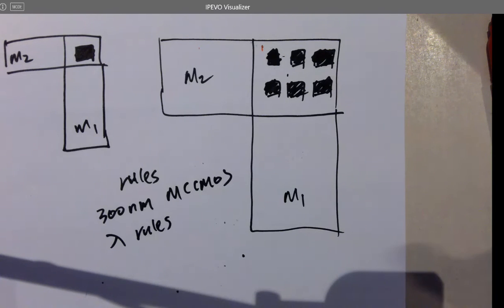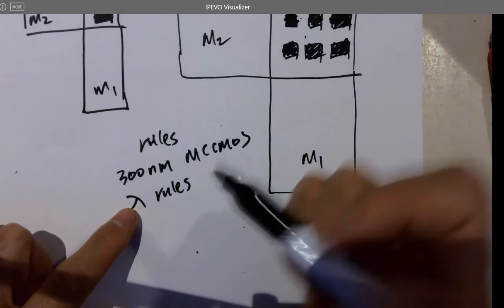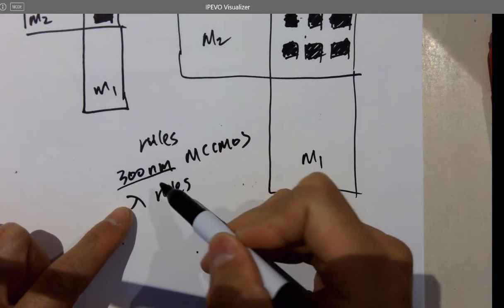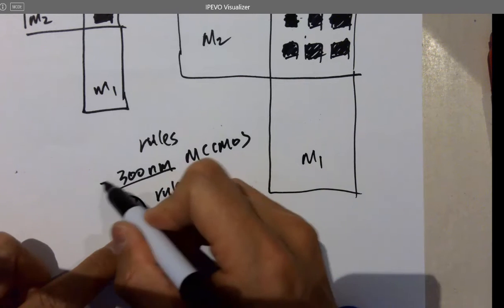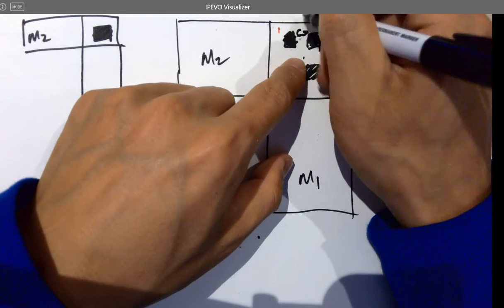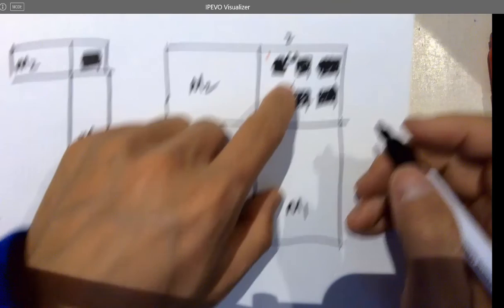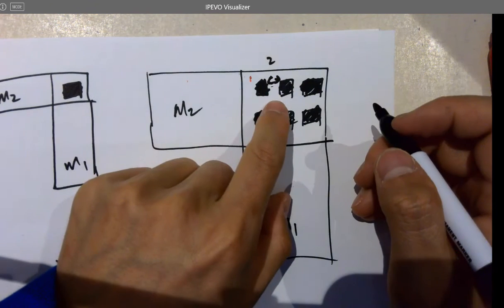So those are the design rules, or standards, for the layout, and you can't see them. They are controlled by the software, and the ones we are using are called Lambda Rules, so it uses a unit. For example, 300 nanometers is 1. So the distance between two vias has to be a minimum of 2, right? So it's going to be 600 nanometers between the two vias.